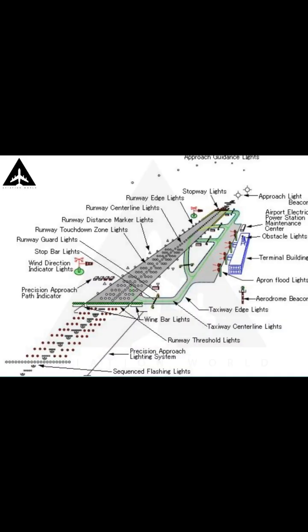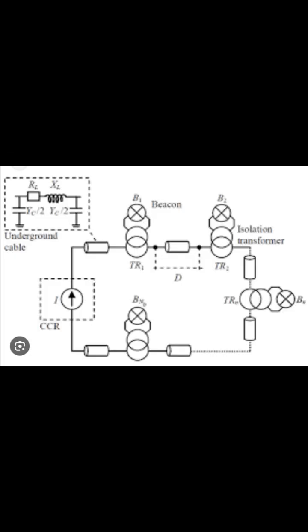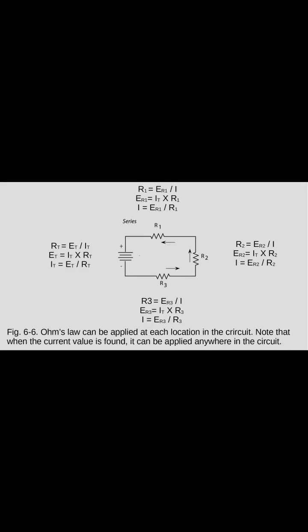The voltage losses caused by the resistance of the copper lines do not permit a practical application of a parallel circuit. The lighting consists of a series circuit with a transformer located at each individual light location. The circuit is connected to a voltage regulator that maintains a constant amperage applied to the circuit. Since the circuit has a constant amperage at each transformer and each lighting unit has equal resistance, each lamp will have the same voltage drop value.